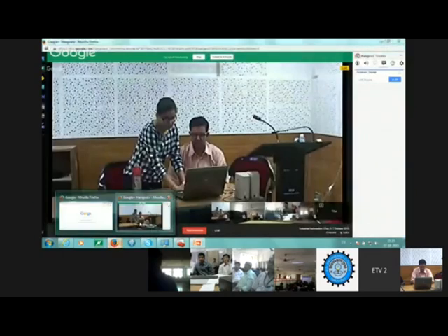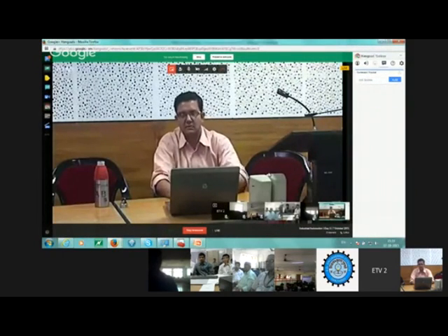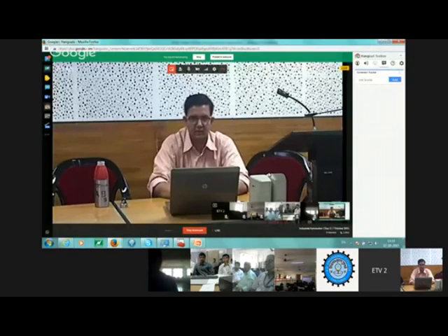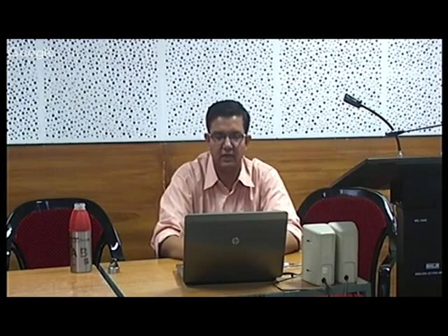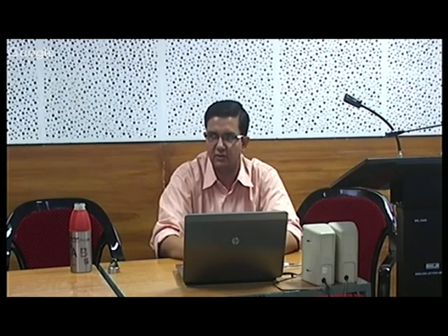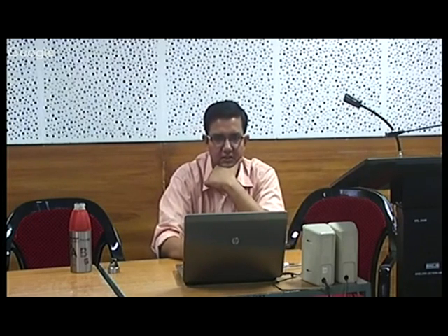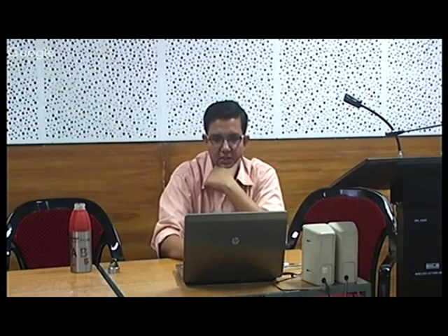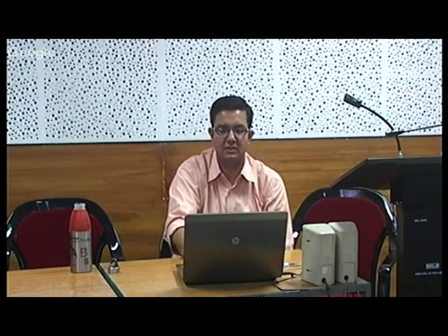Sir, how is the neural network used for fault detection? Basically, the neural network will first be used for training the network using the healthy motor signal. You will require a lot of data from the healthy motor. This data will be used to train the neural network. Then we will have the faulty motor signal. Now we will compare the output of the network from a healthy motor input as well as a faulty motor input. Depending on the difference, we will see the type of fault.